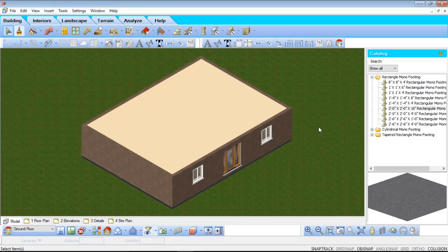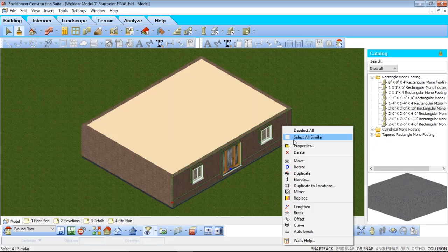And you can see I come back here to my model and nothing has changed. Nothing is updated. So this is an example of how independent properties behave. Previously inserted elements don't update once you make those changes in the building location settings. So I would now need to go in and manually update all of these elements, which I can do. So I'm going to just quickly do that.